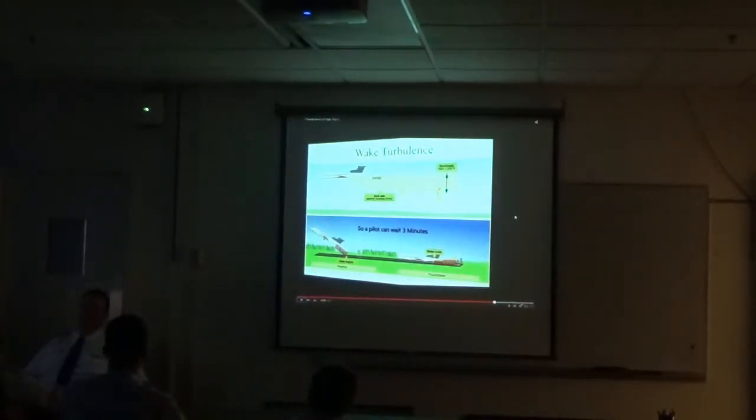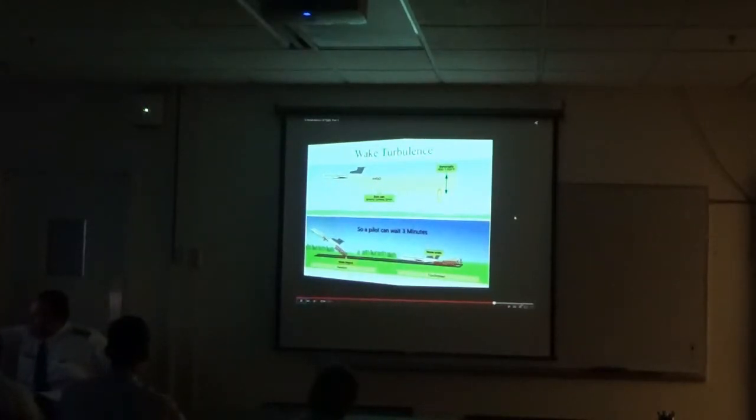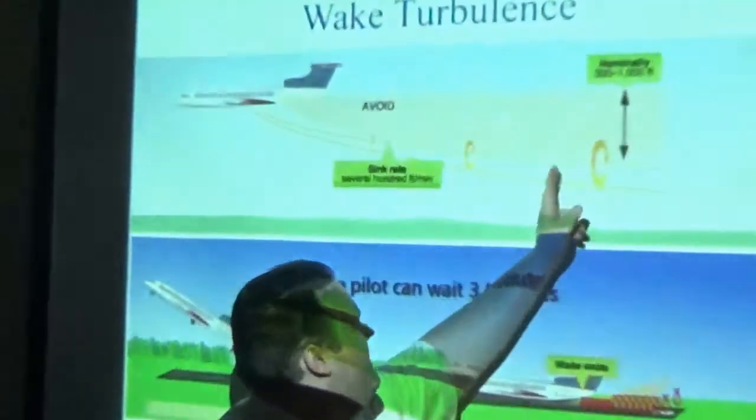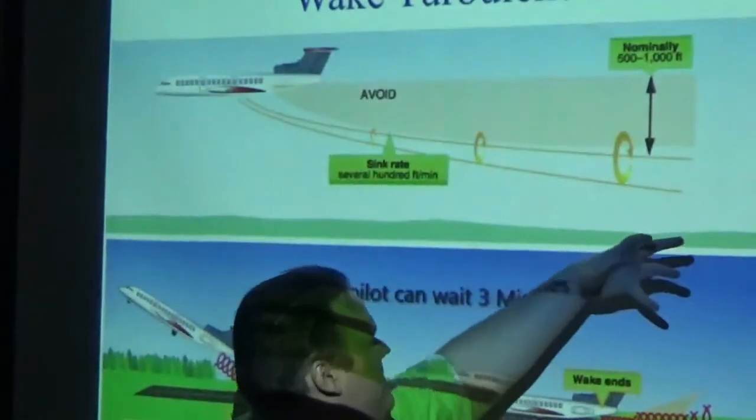Usually, because they're right next to each other, they're right where the wingtip vortices are being created. So they're small enough at that point in time that they're not a hazard. As you can see here, the farther away you are from the aircraft, the bigger the wingtip vortices, and therefore potentially the more dangerous it is, until of course it dissipates.